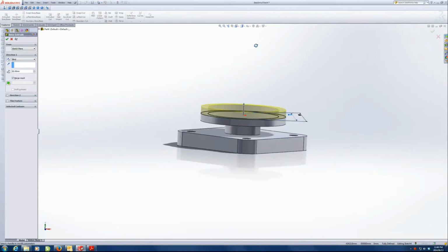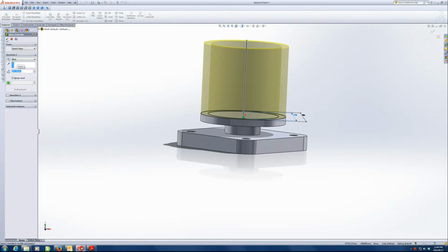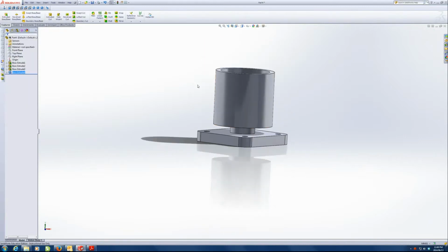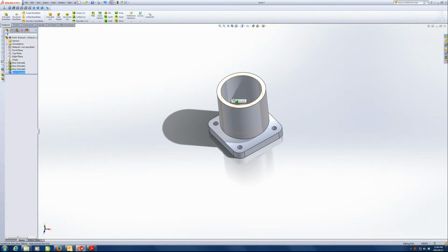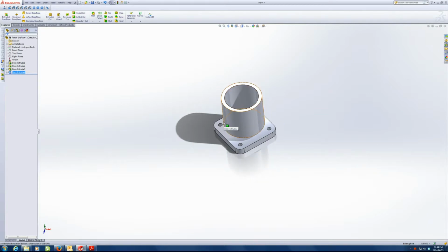We're going to extrude this with a height of 200. I suppose you could also use the shell function if you wanted to. Actually, I'm not too sure about that. You most probably could. Nevertheless, we're drawing it this way.